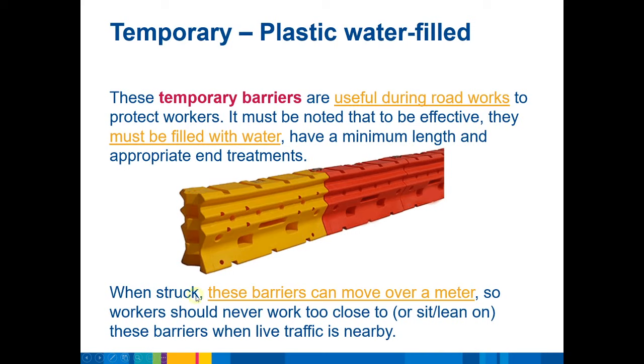Now, even when they're filled with water, these barriers move over a meter when they're struck. So if you find yourself on a job site working around these barriers, don't think of the barrier as a solid wall, because it absolutely is not. Don't lean up against it. Don't stand too close to it. Give yourself at least a meter's clearance between yourself and that flexible or temporary barrier, because if a car or a truck hits it, it will go flying towards you and it will cause just as much injury as the vehicle itself.